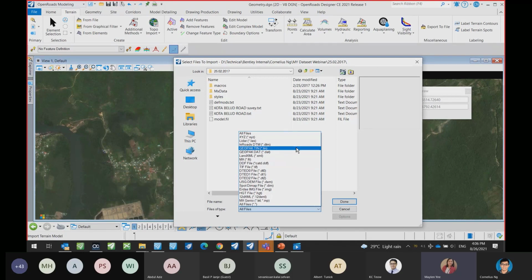The workflow in OpenRoads doesn't work like that, because it's just streaming the aerial photo as well as the map. But if you need probably a terrain, we also have a tool to import Google Surface. Probably you can use that tool, but you have to have Google Earth installed alongside with OpenRoads in order for you to extract terrain.